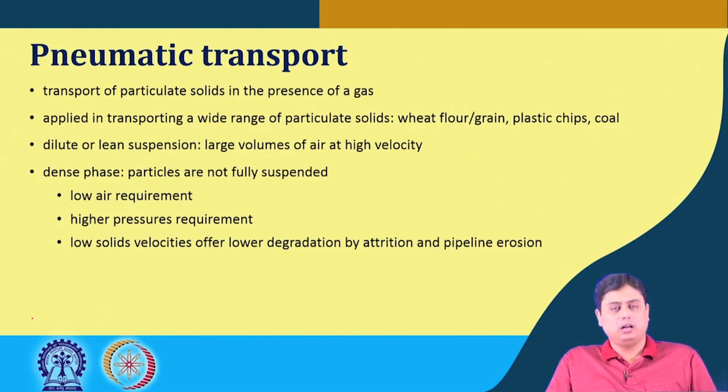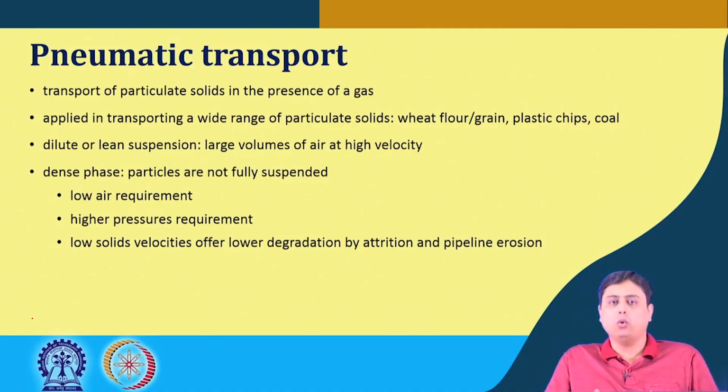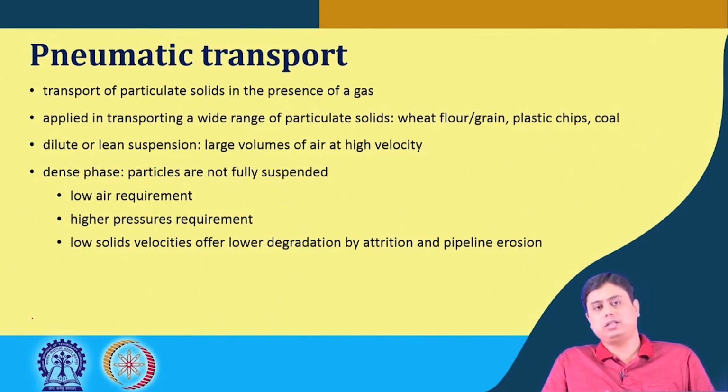Now these are widely applied in transporting a wide range of particles, starting from wheat flour, wheat grain, plastic chips, or even coal. There are two categories or types of pneumatic transport depending on the solids loading or the solids concentration. One is, like the slurry we had, the dilute or lean suspension, and the other one is the dense phase transport.